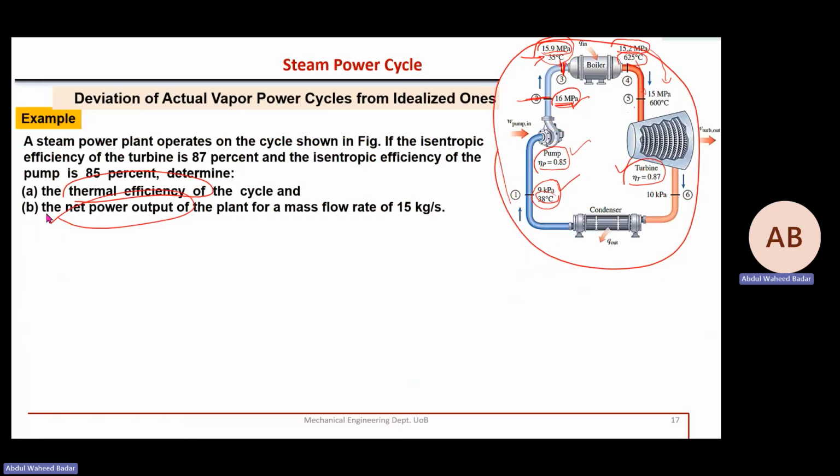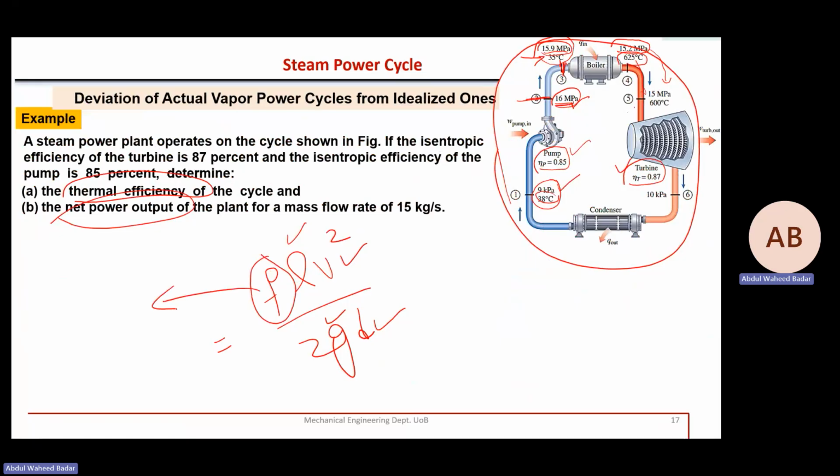So you see that equation, which is responsible for friction loss: f L V squared over 2 g D. Work on it. Velocity, diameter, g. There is also this factor f, which has many parameters affecting it, Reynolds number, roughness. So work on it. Okay, so I stop here and we shall continue. We'll do only this problem in the tutorial class today.